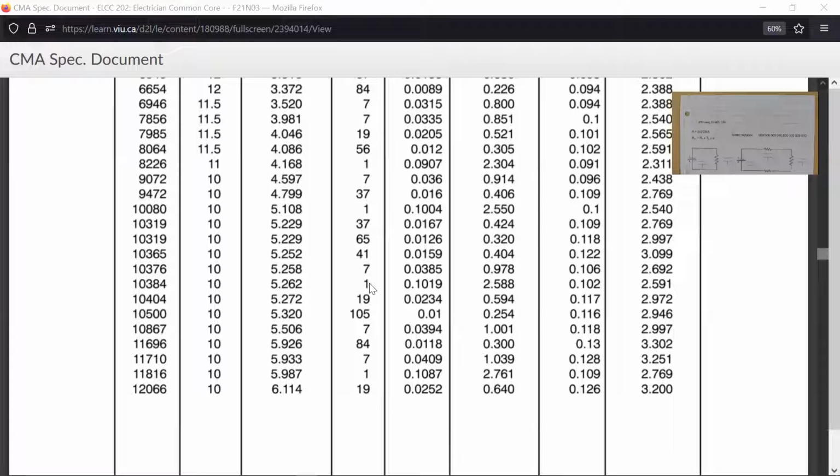If you take any sort of circular thing like this, you make one circle, you take the same one and put it right next to it, and you see how many you can put around it, touching all around it. Geometrically, it's 1, then 7, then 19, then 37, then 61, then 91. So those are our standard sets of strands. In here, we're going to do a single strand, number 10.